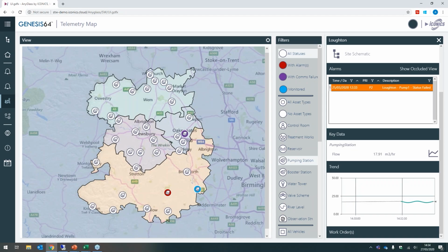of the 600 conveyors was very much a case of filling in an Excel spreadsheet, pointing it to the right function block in the code, so that didn't even specify individual tags, because everything was controlled by function blocks in the PLC code. And then it just became a row of 500-600 rows in Excel, and the whole configuration was created in one go. All the assets were standardized, so the testing was far quicker. And all of these things make it a very good way of deploying your systems.